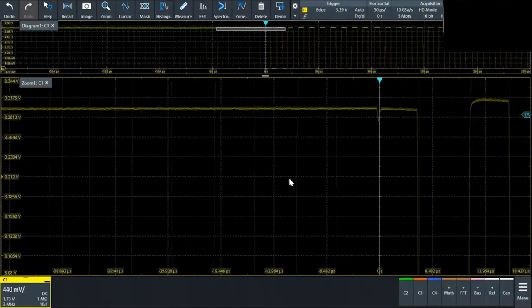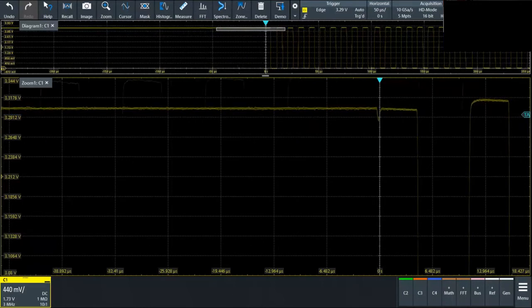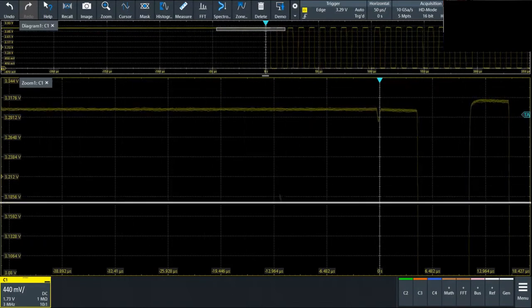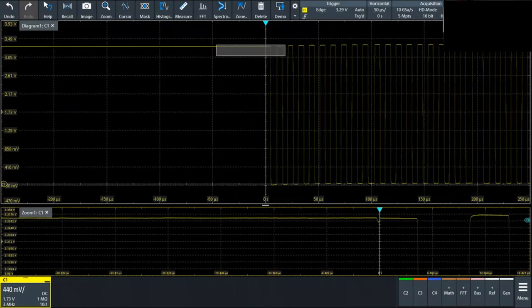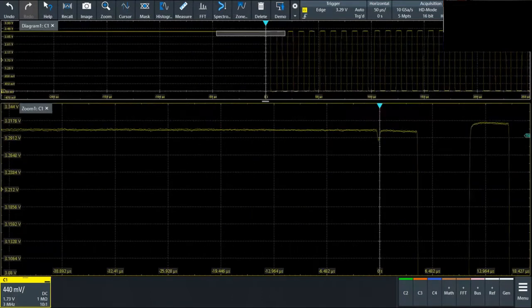If you want to get an idea, this is the zoom waveform on the bottom. We just drag that down. What I'm triggering on is that little tiny pulse in the middle, reliably. We're doing that because our trigger circuit isn't really a circuit at all. It actually uses the digital data from the A to D converter, and even after the filtering, we're able to get the effect of that filtering applied to the trigger. So that's pretty cool. I have fun playing around with that, and I think it's a useful feature.